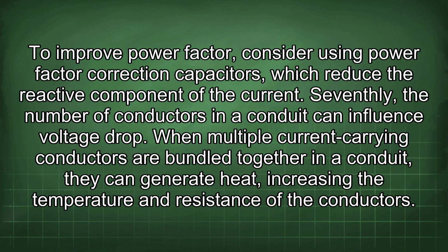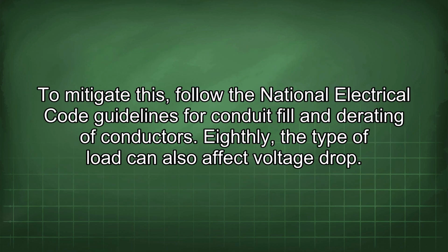Seventhly, the number of conductors in a conduit can influence voltage drop. When multiple current-carrying conductors are bundled together in a conduit, they can generate heat, increasing the temperature and resistance of the conductors. To mitigate this, follow the National Electrical Code guidelines for conduit fill and derating of conductors.